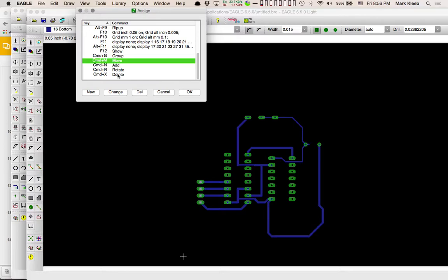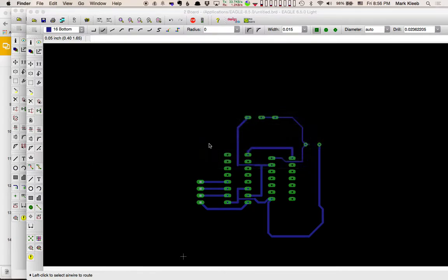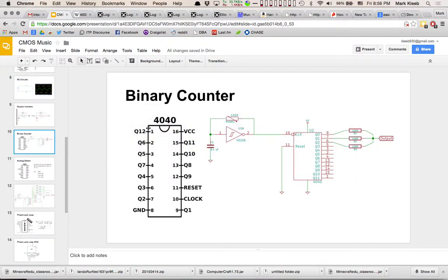Cool. All right. To bring this circuit, we're missing all the resistors. Yeah. So I skipped over that part. There are 3 resistors on each of the outputs. And really the only reason those are in there is because if you sum those together, you're going to get the amplitude of the summation. So those resistors are dropping down the volume of those levels so that when they sum together, they're not blown out.